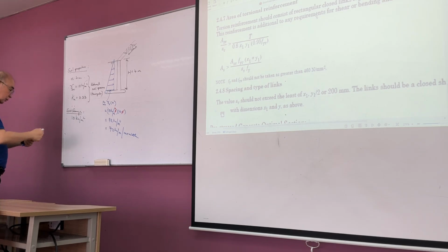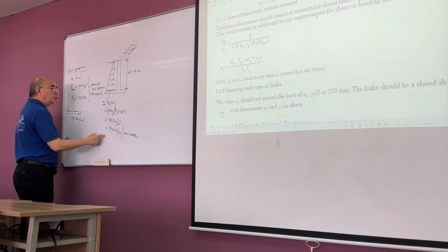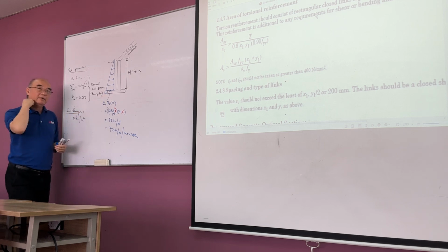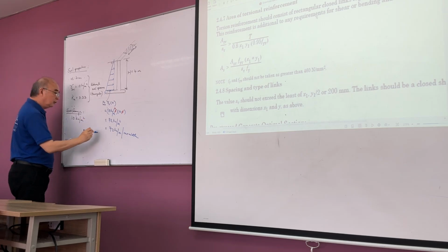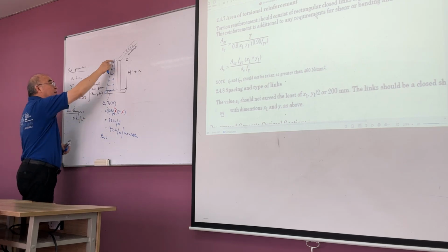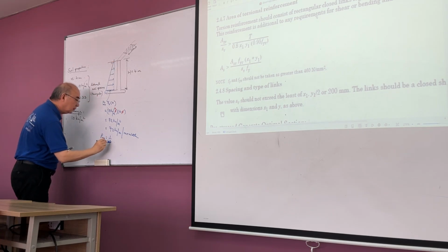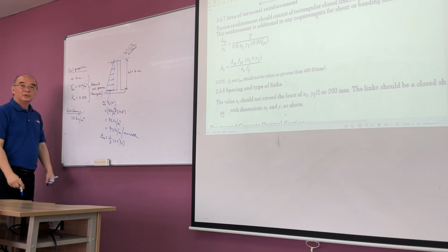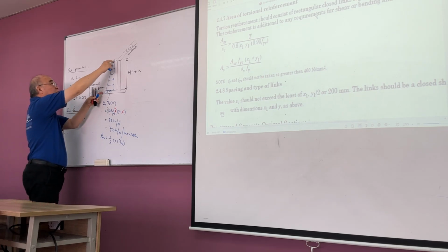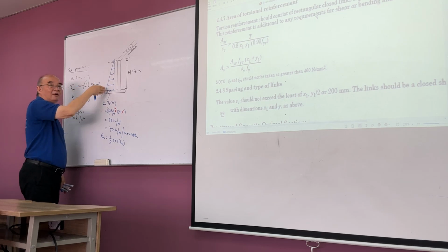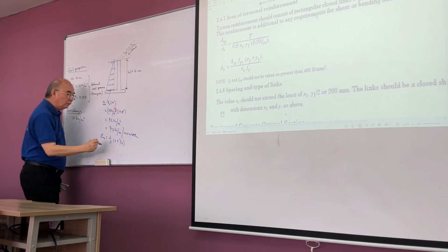So this pressure is the maximum pressure, right? So what is the average pressure? Average soil pressure, let's say P average. Average soil pressure will be half of 0 plus 72, right? Because you are increasing from 0 to 72, right? So average will be half of it, right?